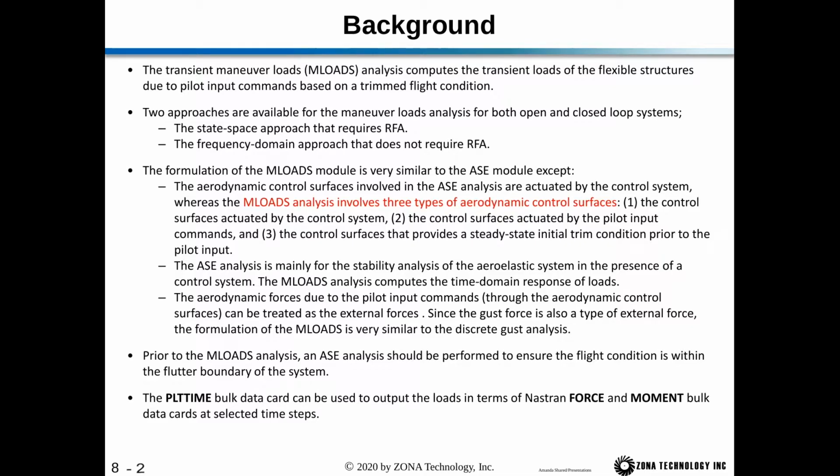It could be a pilot input command to the elevator. You could have a closed loop control system actuating the elevator, and then also you could have a steady state trim deflection to the elevator. And that's fine. You can do that. So next, the ASE analysis is mainly for stability of the aeroelastic system in the presence of a control system, whereas the MLOADS analysis computes the time domain response of the loads.